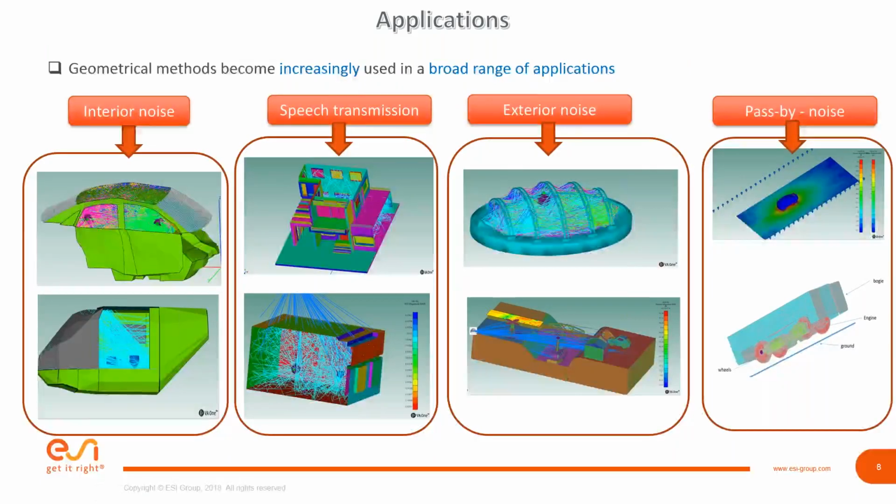So the applications are really unlimited, but these are some of the more normal ones. Interior noise. The original speech clarity was intended for train cabins, aircraft cabins, things with PA systems. Larger, where you expect maybe not an equal response. It's a large cabin, a lot of absorption. Some points in the cabin have louder or softer responses, different ratios of direct and reflected sound.